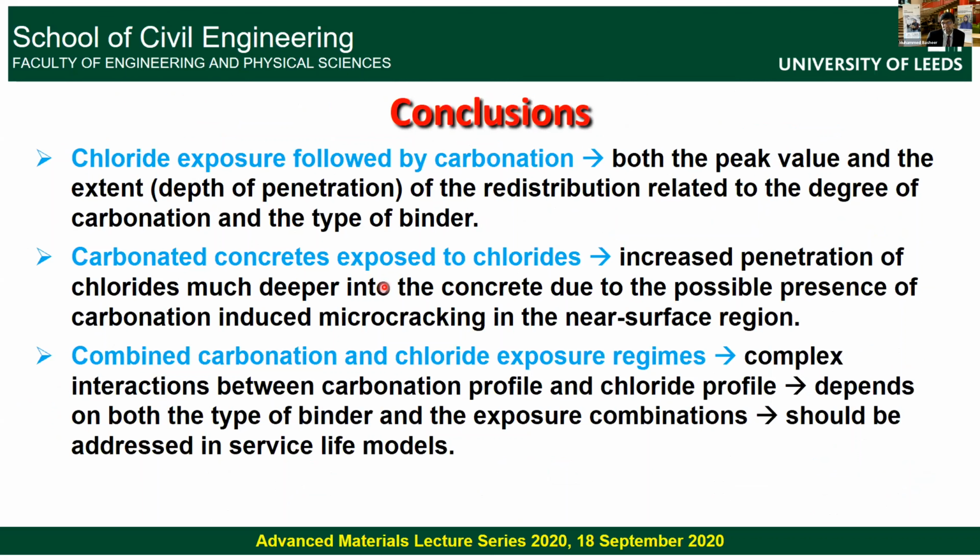Carbonated concretes exposed to chlorides increase the penetration of chlorides much deeper into the concrete. So that means carbonation is causing more penetration into the concrete. And in the combined carbonation and chloride exposure regime, there is a complex interaction between carbonation profile and chlorides. We need to take that into account in service life models.